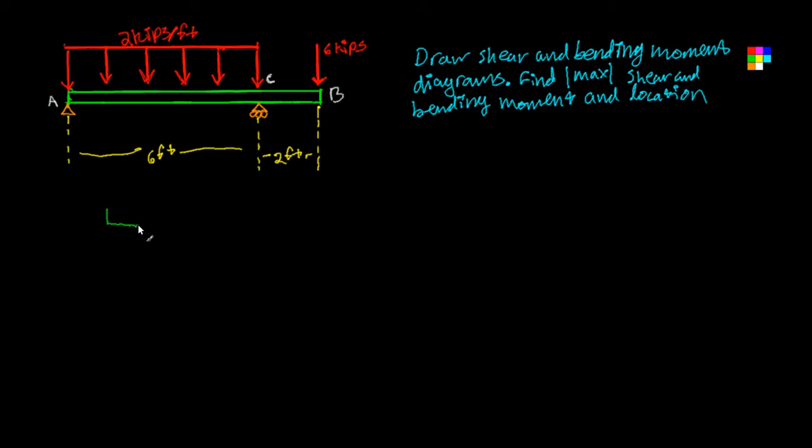So maybe you already know, but I'll just draw it out. If you take a slice right through here of this, we can draw in three forces. We've got the compressive or tensile force, we've got a bending moment, and then we've got our shear force. So that's our M. Shear is represented by a V for some reason, so that's how you'll see it. And so we don't care about this compressive force. There actually is nothing happening in the x direction. We want to know our V and our M.